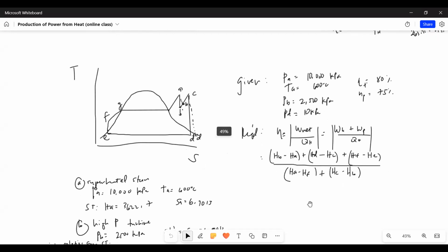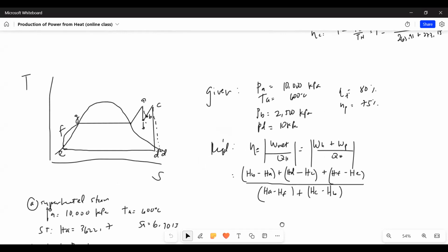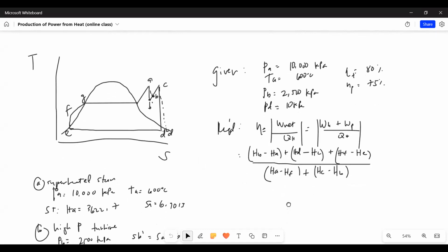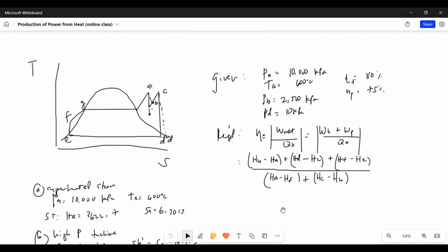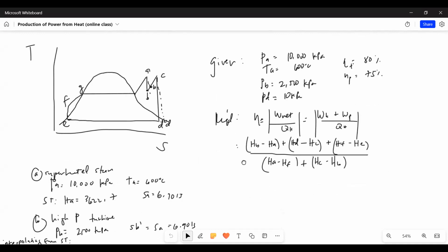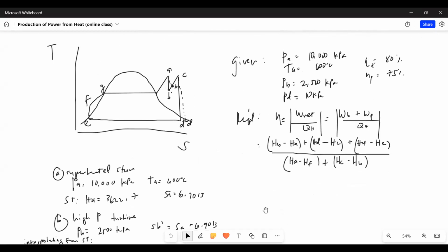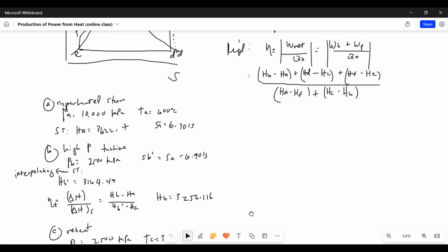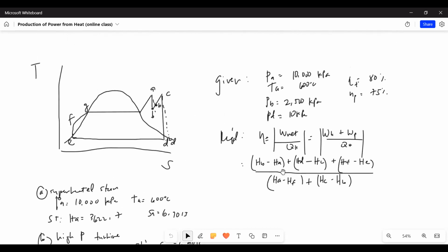We finished solving this problem. Basically, what we're being asked is the efficiency of this Rankine cycle with superheat and reheat. So just like in our previous problems, we solved for the property at each point, or in the inlet or outlet of each device. But the difference here is that we have a high pressure turbine and a low pressure turbine. And because of that, our efficiency equation would have to accommodate those two turbines.